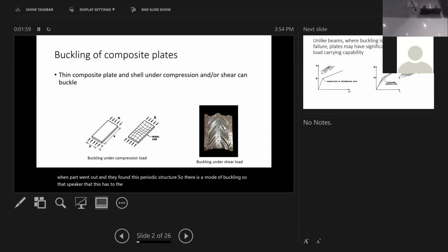We talk about the first mode, second mode, third mode, just like vibration modes. There are buckling modes. Like a plate under compression, it could develop any number of different modes. They have different threshold loads. It could have one dip, one protrusion, or two protrusions, one dip. We're talking about different half waves. Okay, that's the buckling phenomenon.